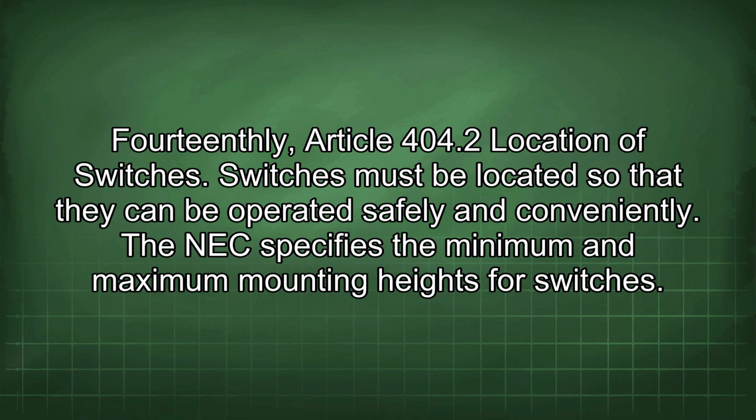Fourteenth, Article 404.2 Location of switches. Switches must be located so that they can be operated safely and conveniently. The NEC specifies the minimum and maximum mounting heights for switches.